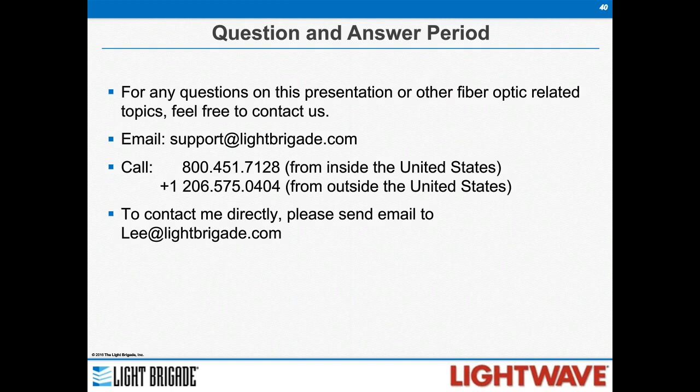So the next question is, OTDRs are primarily used to measure insertion loss and return loss for longer cables. Are they effective for short cables, such as 1 foot breakout cassettes, or should some other tool be used? So I think the question is, can you use an OTDR to look at a cassette? For most OTDRs, a cassette that's got like a 1 foot or a 1 meter length of cable between the back end and the front end will look like one event.